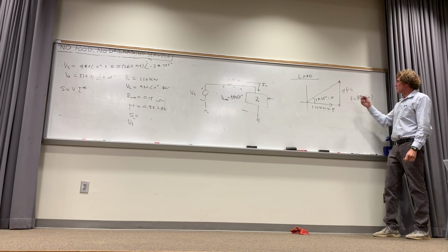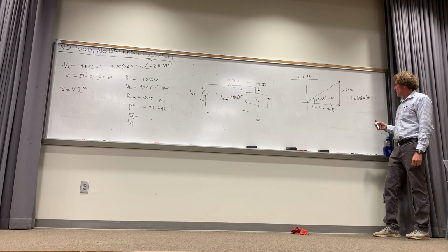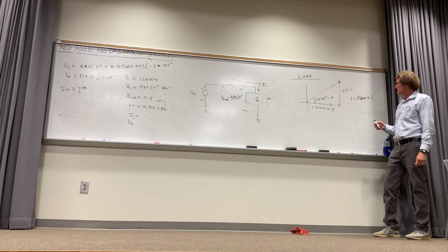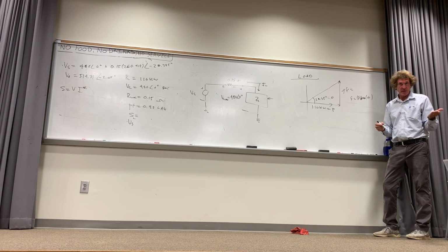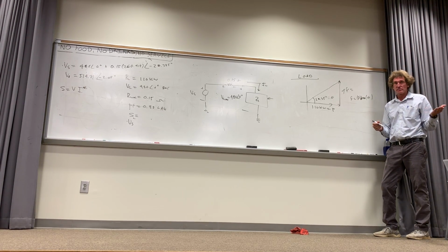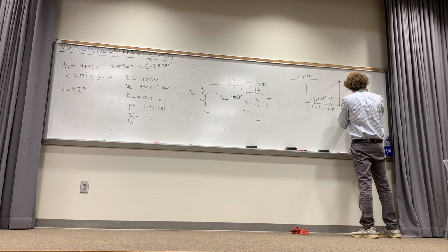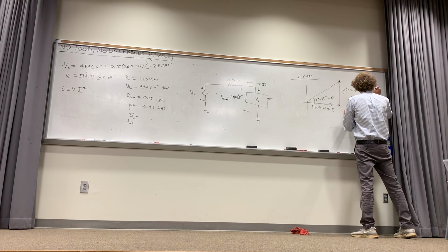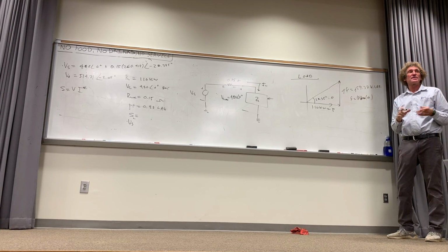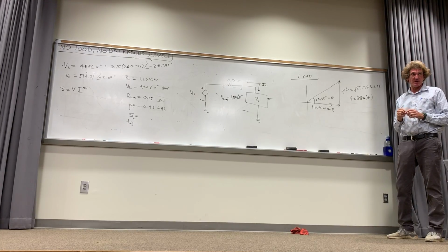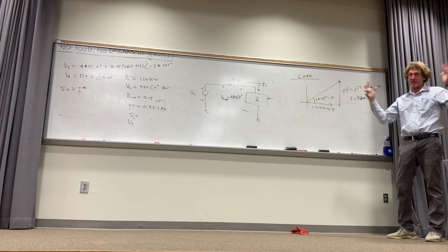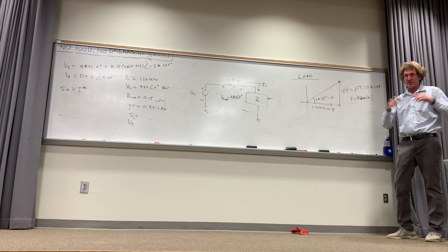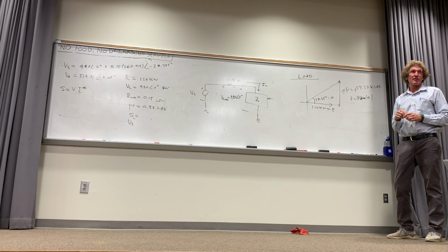So that's JQ. What do you get for Q here, by the way? Take 110 kW, or 110 times 10 to the third, times the tangent of 28.35. I can't do that one in my head. Anybody? 59.37. So it's J 59.37, and that would be kVAR. That's volt-amp reactive. The R indicates that that power is reactive power. It's not absorbed or dissipated. It's power that goes into the unit, then comes out of the unit, if you think of it that way. Energy into, out of, into, out of. It's just swooshing around. Everybody with me?